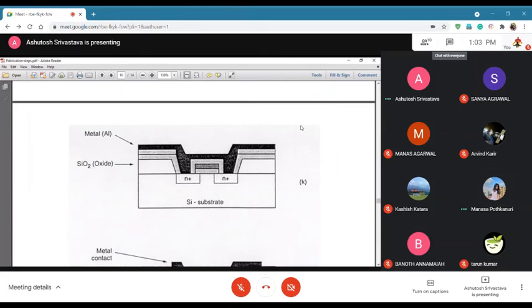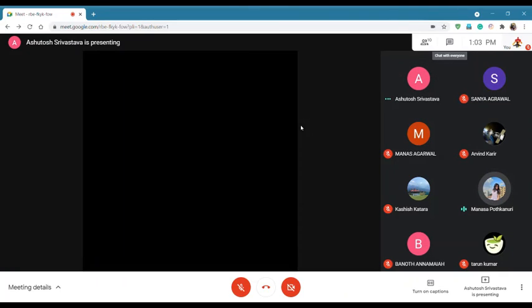So for NOR, we actually have the PMOS in series, and that is connected to our VDD, and to that we connect the two NMOS in parallel. Okay, if we do that, I think you are going in the right direction. Can you just show it to us? Sir, how, like, I have to draw? Yeah, just draw.